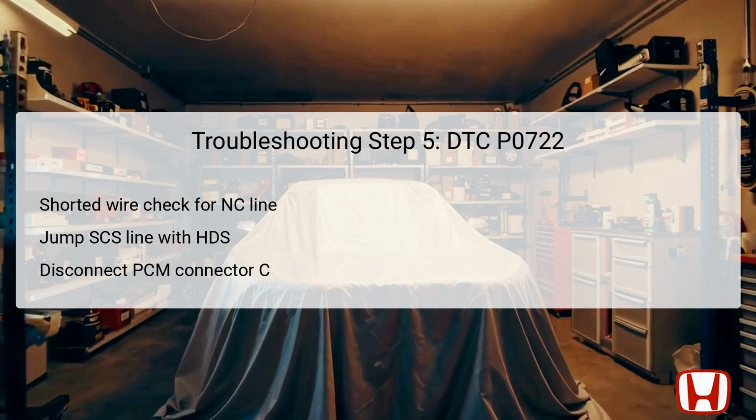Start by ensuring the vehicle is in the off-lock mode for safety before proceeding. Activate the SRS, Supplemental Restraint System, line with the HDS to facilitate accurate testing, and allow a minimum waiting time of 1 minute for the system to be ready. Afterward, disconnect the PCM connector C51P to isolate the electronic control unit from the system. A continuity test will then be conducted between test points 1 and 2, which checks the path from the output shaft speed sensor to the PCM.